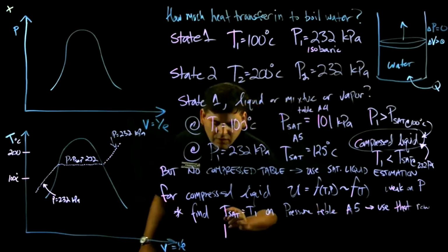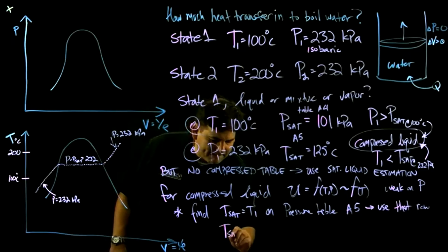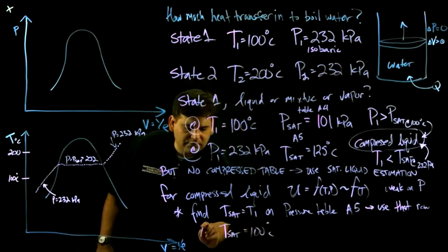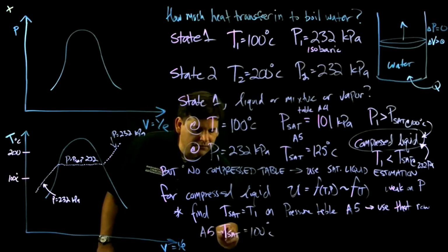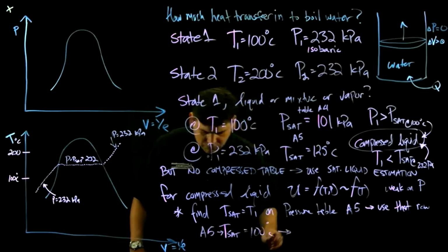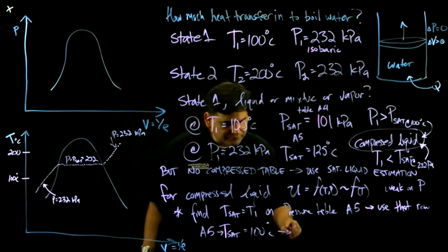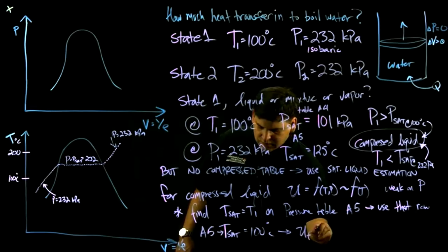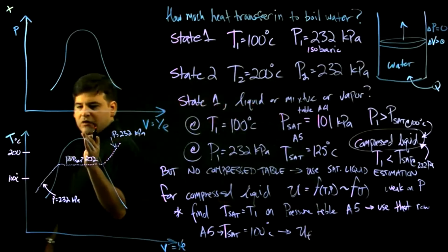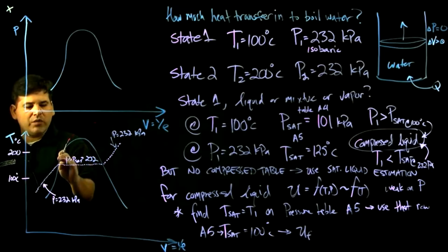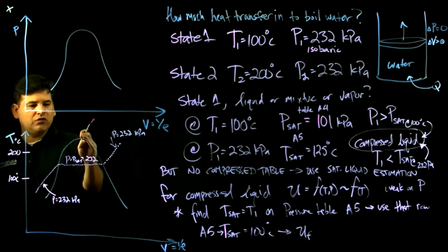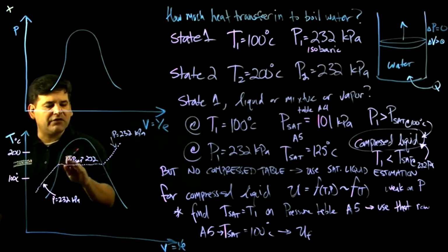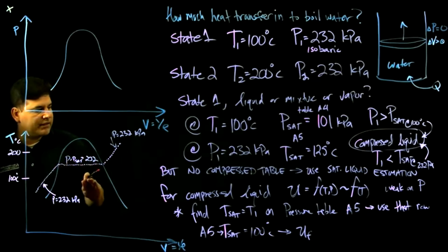So for example, where T sat equals 100 Celsius on the P table, you can read off values that you can say UF is the values of the internal energy on this branch, the fluid branch. UV would be the table of values on this saturated vapor branch. And if you're in between there, you would have to know the quality.